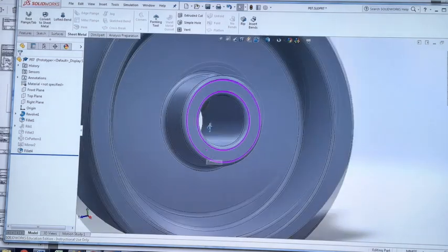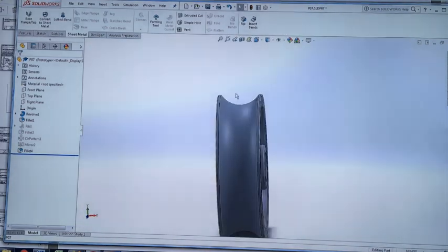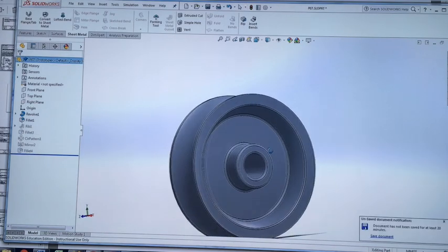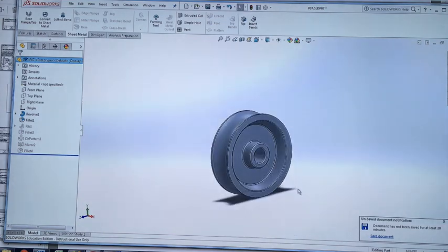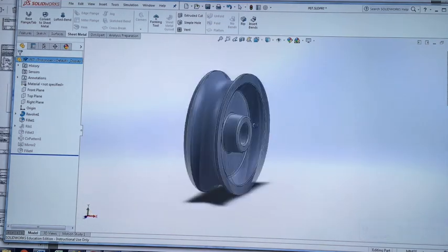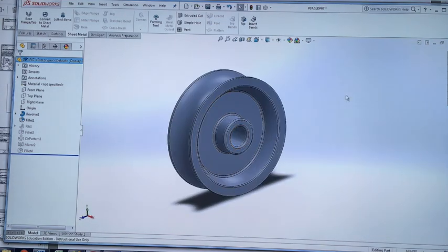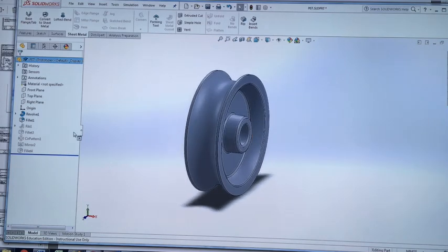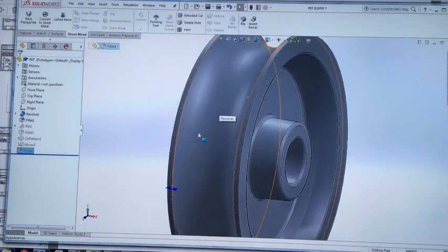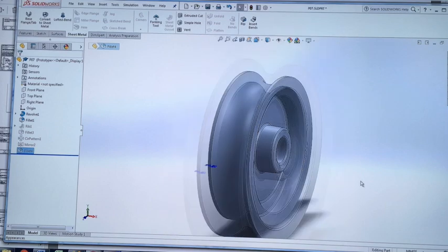That's going to turn that off. I'm also going to suppress the fillet that's on this very outside edge. Okay, so I'm basically at a blank type shape. Just the outside edge, because there was a small half mil fillet on these two outside edges, which I've turned off.